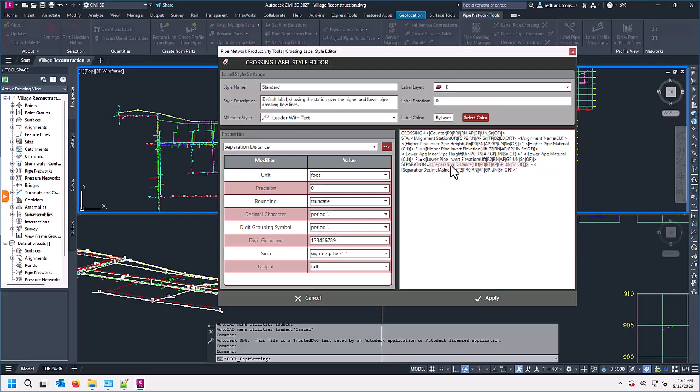to get me to just the foot unit. And then I've got my foot dash, and then I have this expression that I'm pulling in that does the same thing but divides that by 12 to get to inches. And that gives me the inch property. And so you can control the precision on that if you don't want to dial into, say, a 1/4 inch or 1/2 inch.